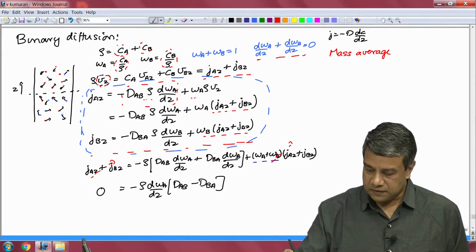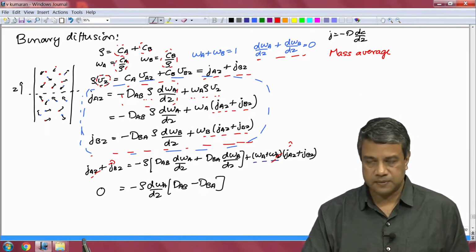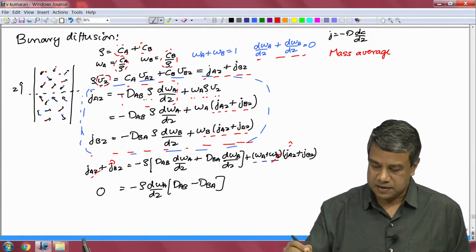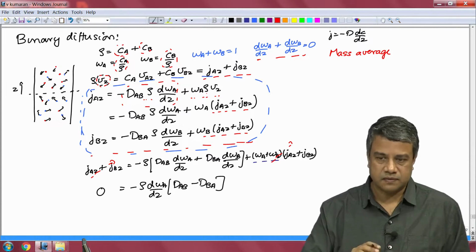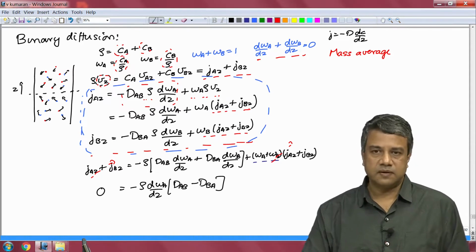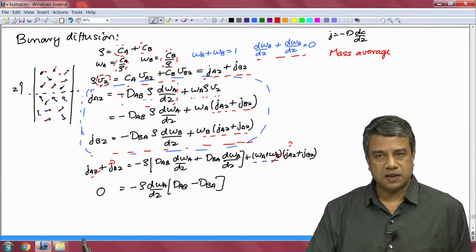The flux of A molecules due to the center of mass velocity is wA rho Vz. And if I express rho Vz, the mass flow rate, as the sum of the flow rates of the two species, I get this expression, and therefore, you can see that you have a flux appearing on the right side as well of both A and B.